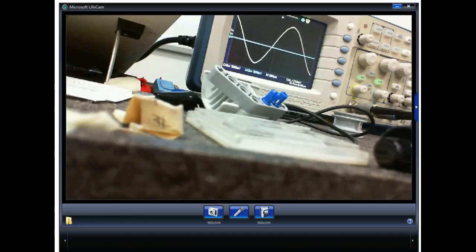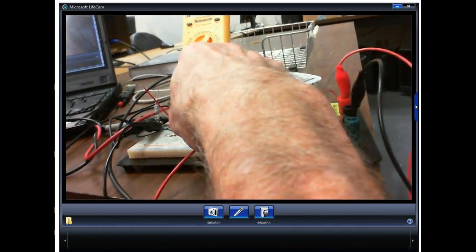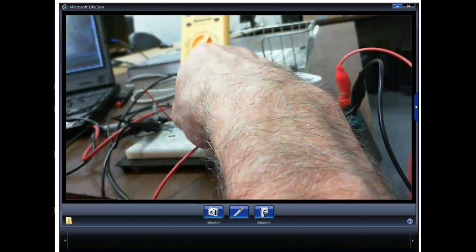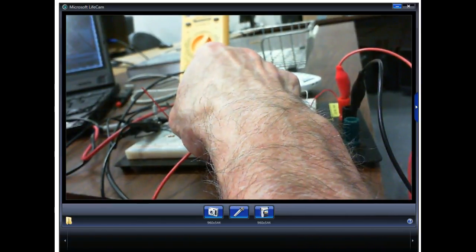What we're going to do next? The next ones are going to be hard to simulate. So we're going to open the collector, but remember when you open the collector, we're not going to measure at the collector anymore. We're going to measure where the collector was supposed to be connected, right? So what we'll do is take our transistor and shift the collector lead one over.